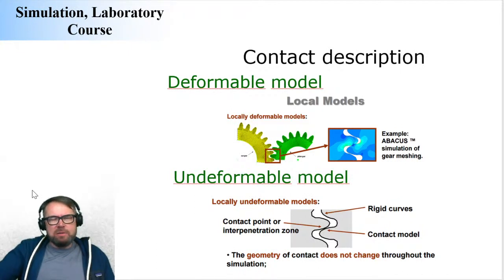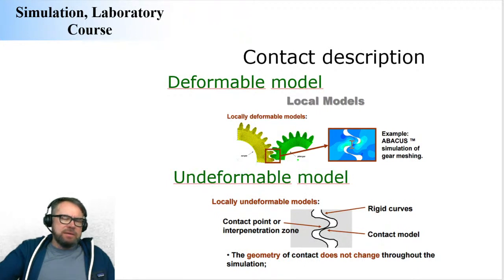The bodies cannot really penetrate each other, but there is a local deformation. To describe that accurately, you should model your bodies as flexible bodies. And you should look at the local deformation of, let's say, a sprocket system: how the teeth are contacting and how they deform because of these contacts.